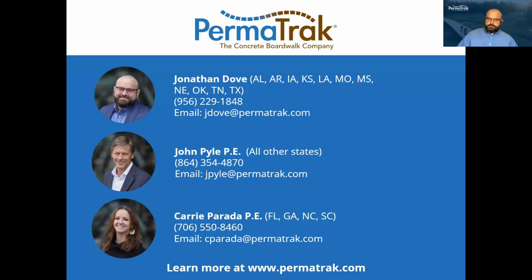Now, how many borings do you have to do? If you're a 100 or 200 foot boardwalk system, I would say as a minimum, I would do 2, maybe 3 borings on something like that. But I would leave it up to the geotechnical engineer to potentially say we might need more if you're getting a large variation in the soil profiles. You may very much get drastically different results from one side to the other. And we've seen that happen where that doesn't play out very well for the owner. So have some more done. I would think on a 100 or 200 foot boardwalk, you shouldn't need any more than 5 or 6.